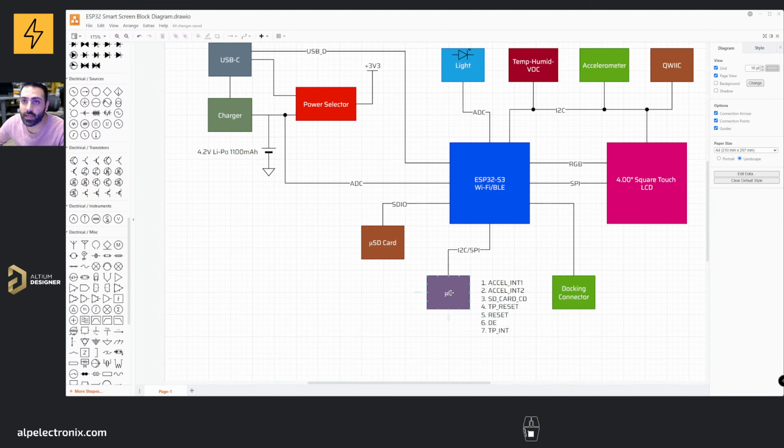And then we will have another microcontroller. The purpose here is to use this as a GPIO extender, because a normal I2C GPIO extender is around 50 cents or something, and this one is like 60 or 70 cents. So we can have more features in this microcontroller, but the disadvantage is that you need to program this one as well. Of course, we will program this one and then ship it with the program in it.